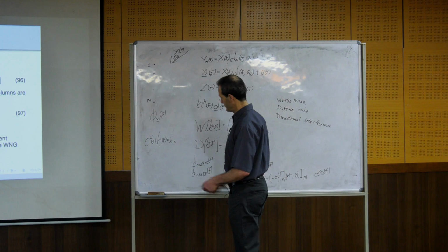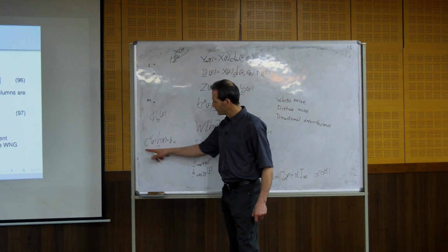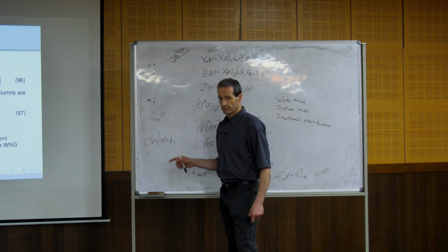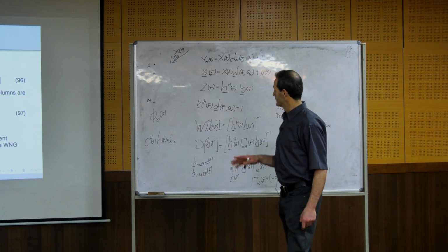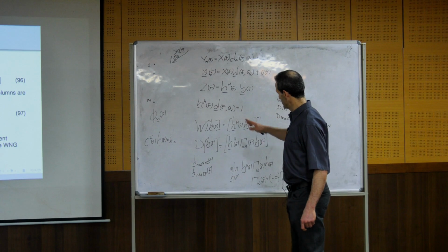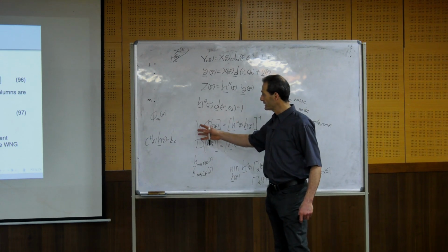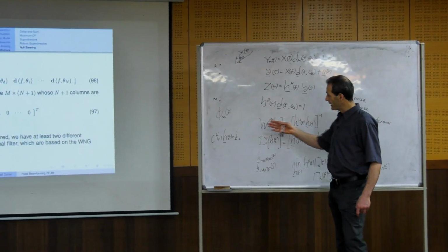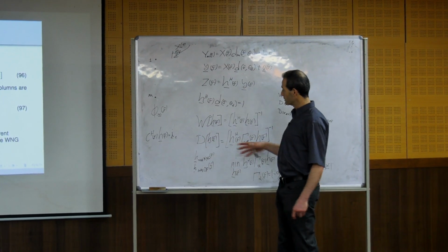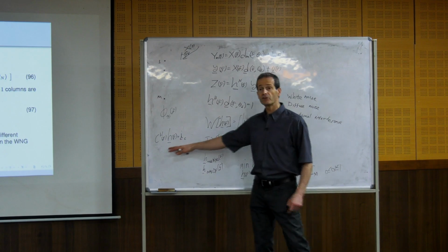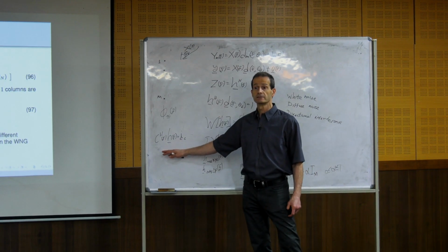So when we have this matrix of constraints, we know how to solve it. We need to find the beamformer that either maximizes the white noise gain under these constraints, or we can find the beamformer that maximizes the directivity under these constraints.